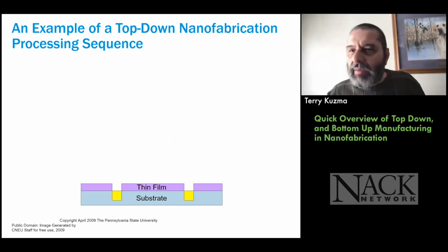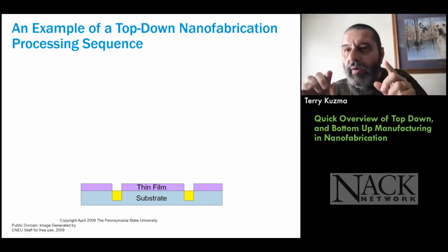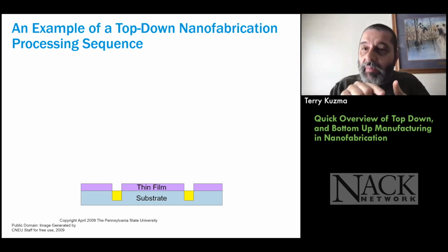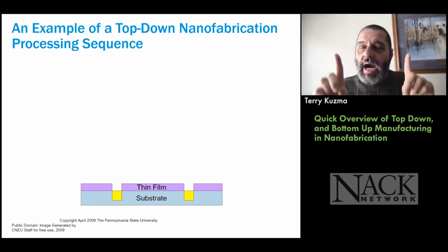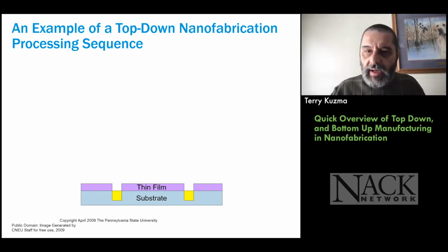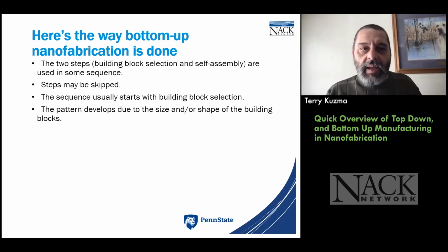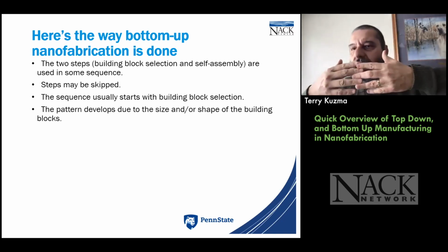So it said it's complete, but actually what I would do is, see where it says the words thin film? That purple, that's oxide. On top of that, I would put a metal, and that would be the gate. And then I'd put wires into the drain and source, and then that would be my transistor. So there should be another step where we put the gate on there. So this is bottom up. And basically we do a couple steps. What we're going to do is we do these sequences, but there's allowed states. And I look at it as like Velcro that only sticks to certain Velcro.